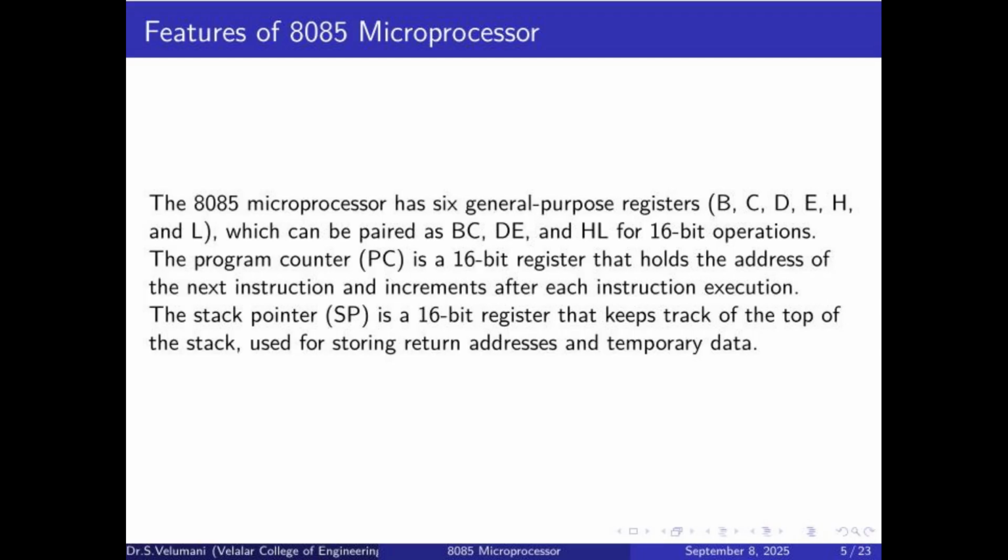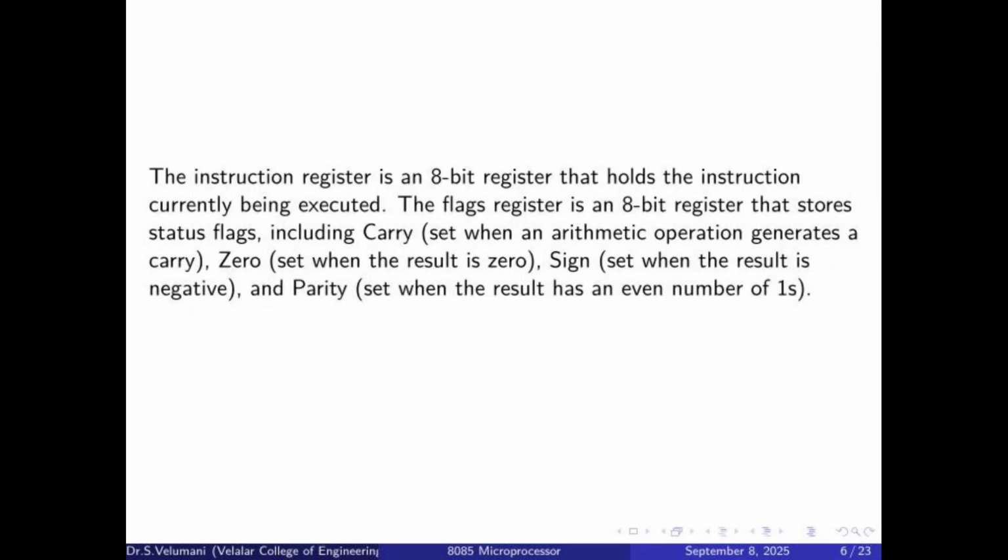Stack pointer, simply called SP, is a 16-bit register that keeps track of the top of the stack, used for storing return addresses and temporary data. The instruction register is an 8-bit register that holds the instruction currently being executed.